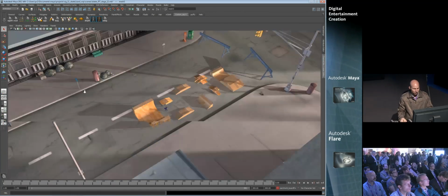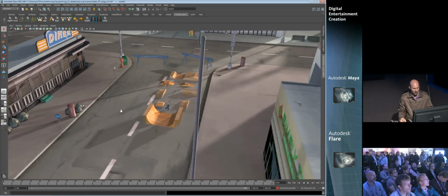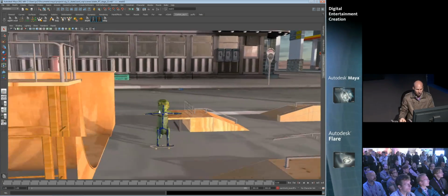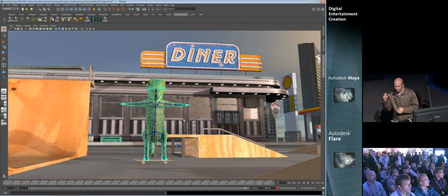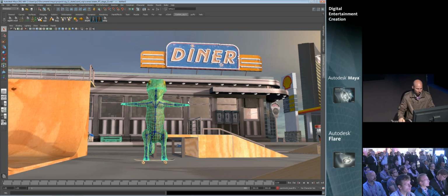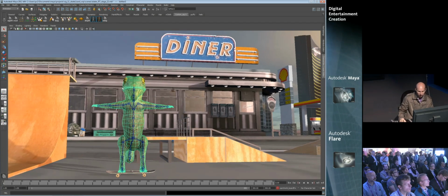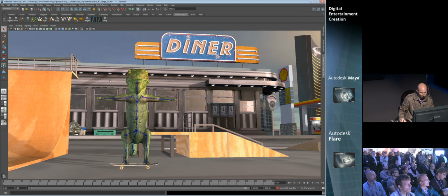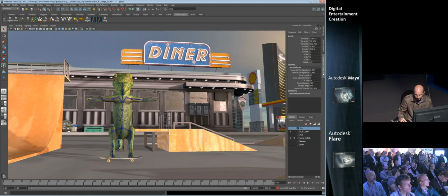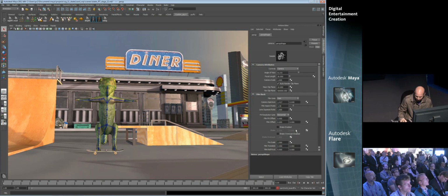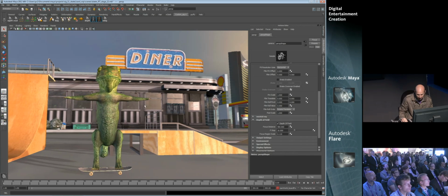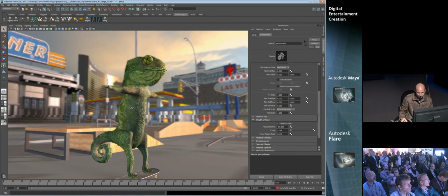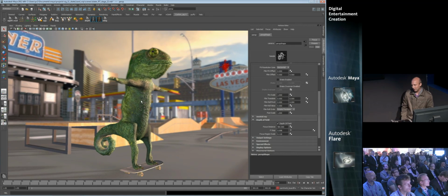If you look at my scene here, if I zoom really far out, obviously the scale of that character, he's kind of small. So to get this shot looking correct, I'd want to have some depth of field in there to really convey the message of this kind of shallow depth of field, or a fast glass on the camera, if you would. We can do that in Viewport 2.0. So if we select this camera and bring up the attributes for it, go to depth of field, turn that on, drop that f-stop down and get that sort of shallow depth of field. You can see now that we really convey the sense of scale a lot better once we start to put that shallow depth of field in there.